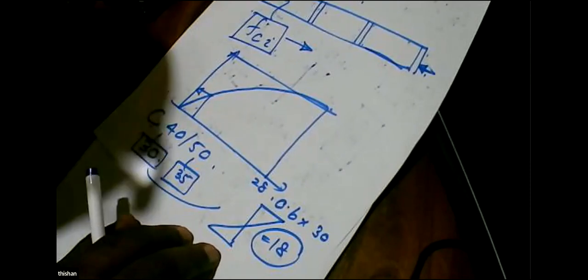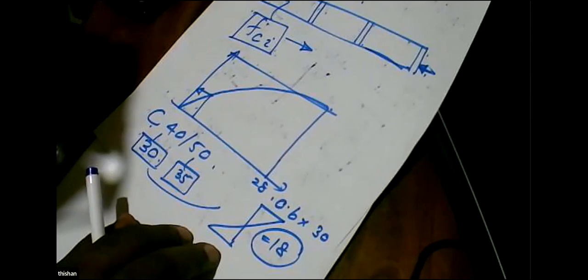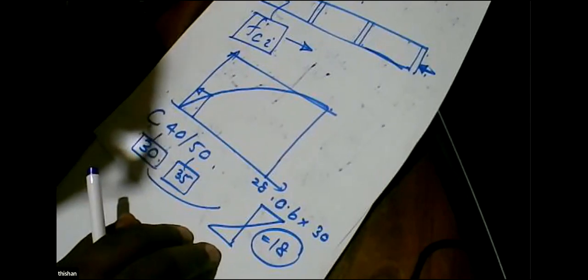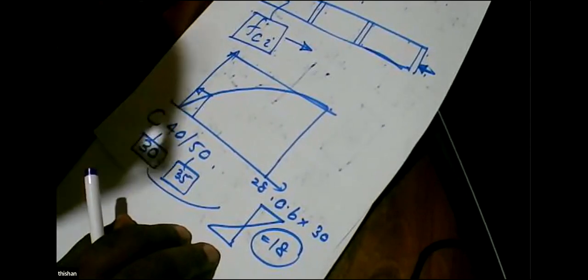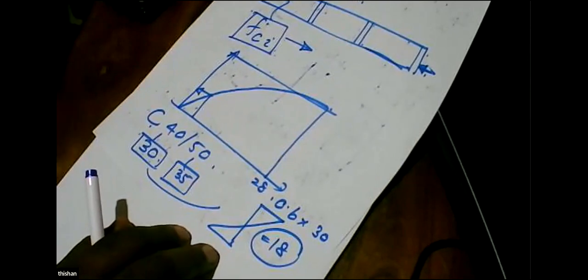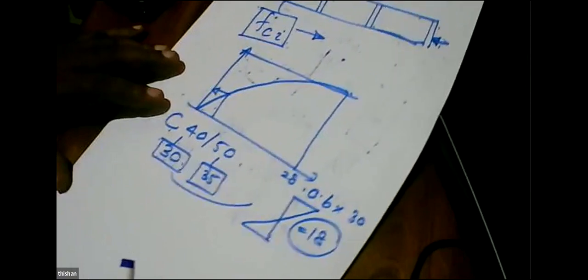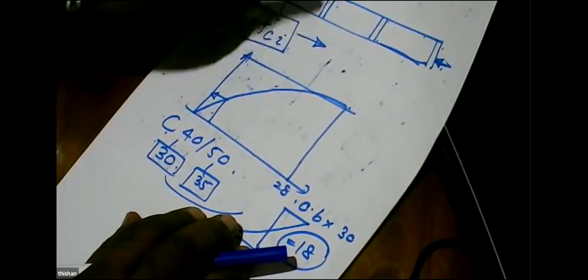Then you say, now it's okay. Let's cut the wires and make the casting bed free for the next batch. So that's why we don't wait until the concrete has gained its full strength to do the pre-stressing transfer. We always do it at an early stage.